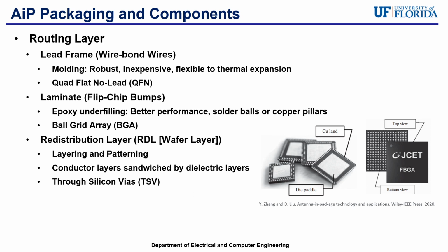For ball grid array and quad flat no lead, these are typically slightly more common than RDLs. And it's because the choice of BGA or QFN package types is typically dependent on the requirement of input output counts by the die, and because ball grid array packages usually have higher input output counts with the same body size, BGAs are more common. The figure shows QFNs and BGAs respectively.